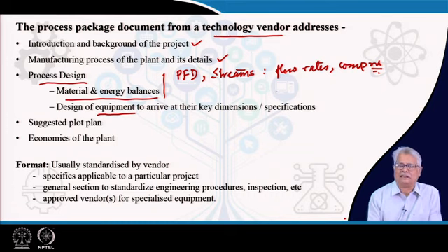Typically, I will put it like this: if you are having a particular technology which asks for a water supply at a temperature of 25 degrees centigrade, and you do not have a utility which supplies cooling water at 25 degrees centigrade, either that utility has to be managed and provided, or the design has to be modified in some way. So, quite naturally, for detailed engineering design procedures, you require sufficient information on what may be available as utility as well as in off-site facilities.